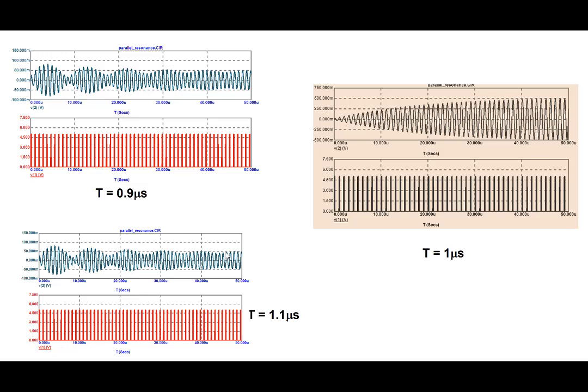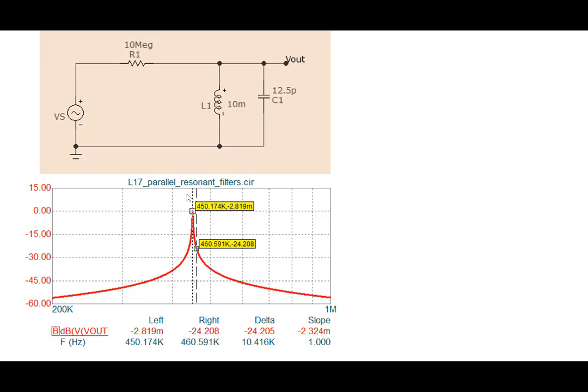So this is the concept that we want to utilize for obtaining very high selectivity. Use the concept of resonance. The signal that you want to capture or pass, let that signal match the resonant frequency of the circuit, and the rest of the signals will be out of resonance with the circuit and will get naturally attenuated and rejected. So let me show an example here.